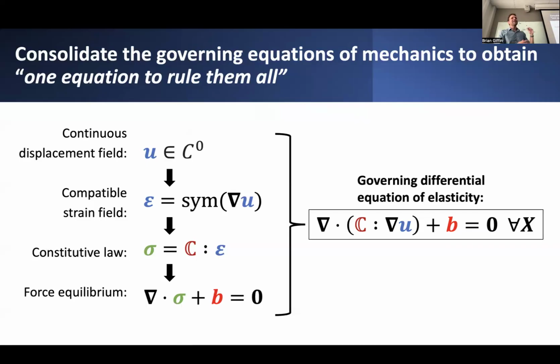This is a statement of equilibrium, which must be satisfied at every single point in the domain. So at every single location, or every single small chunk of material that we could look at in the domain, this equation has to be satisfied there and everywhere. So you could say there are only three equations, but in reality there are as many equations as you have points in the domain, which implies, if there's an uncountably infinite number of points to consider, an infinite number of these equations that we have to solve.